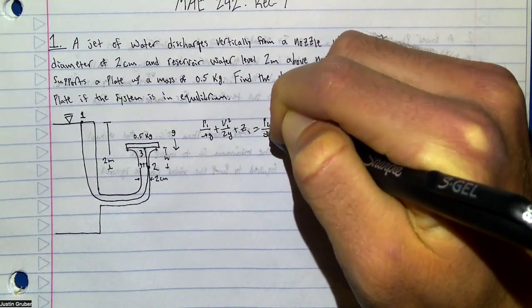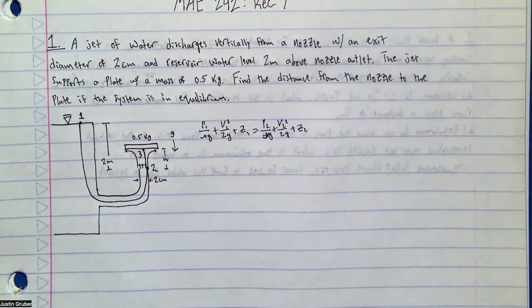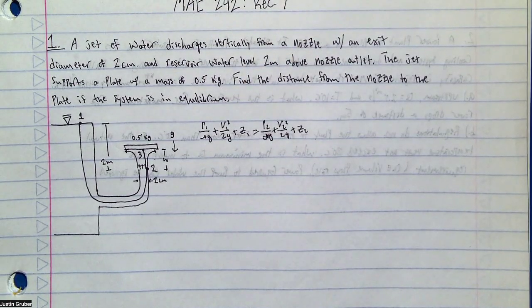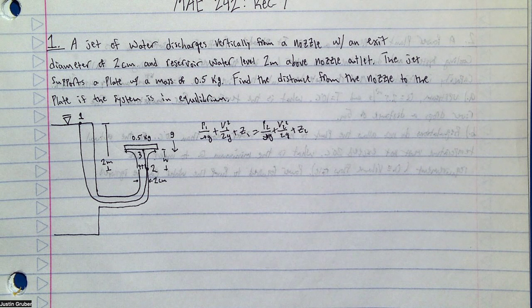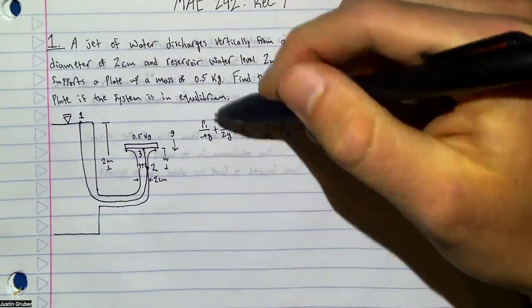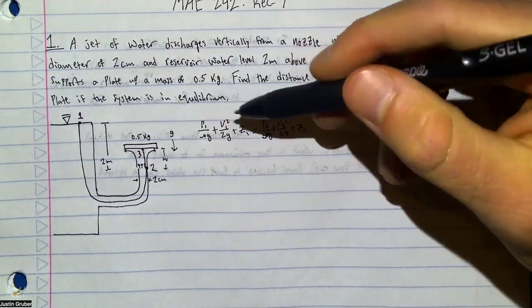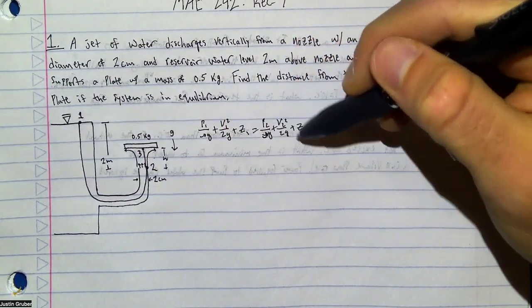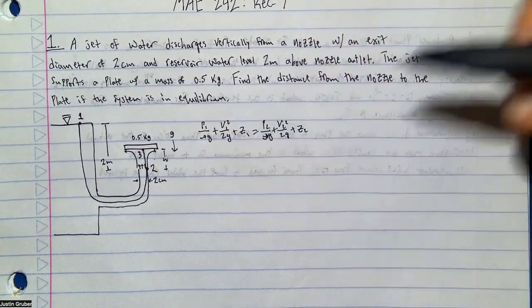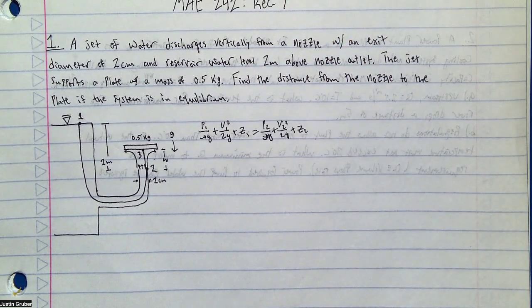I know my rhos. Those are rhos, that's density right there, where we can just use the density of the water as 1,000. And so we can make some additional assumptions right now. You can see these terms on the left, since everything here is equal to a constant, you can set them equal to each other along the streamline and make relations with that.